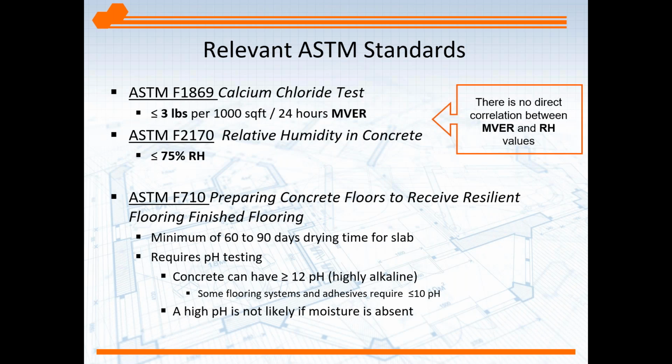Also, ASTM F710, we saw that earlier. That's where we got the values of 3 pounds and 75%. But there's other prescriptions in this standard as far as dry time, which can be affected by ambient temperature and humidity. Also, pH testing is required as part of this standard.